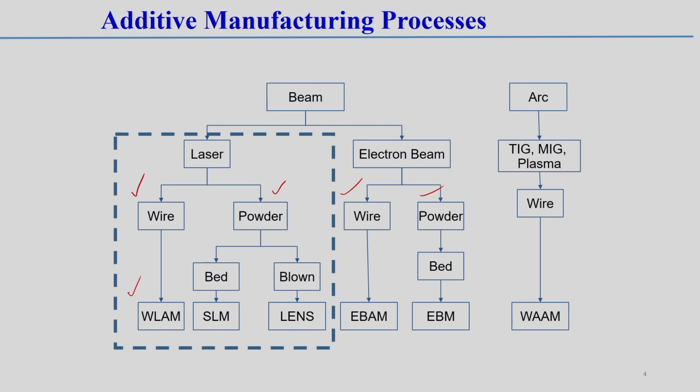So, the electron beam technology is the costlier one compared to the laser, but in another way it is advantageous: the manufactured component can be kept in a protected environment, such that contamination or oxide formation from the outside atmosphere can be eliminated completely. Even though it is a costly technology, if you want to achieve an almost defect free component, or a highly precise component, or we are handling very costly material, then electron beam technology can be much more suitable as compared to the laser beam.